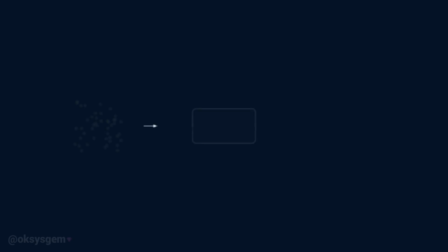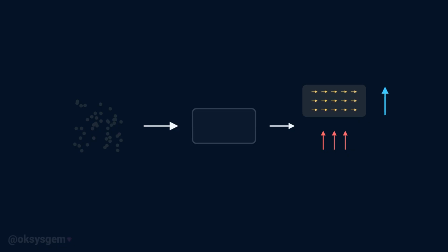Unlike a solid piece of metallic iron, ferrite is a ceramic. The ingredients can be processed into a powder, shaped, and heated until the particles bond together into a rigid magnetic material. During manufacturing, magnetic fields can help orient the microscopic structure so that the finished magnet develops a preferred magnetic direction. Ferrite magnets are not particularly powerful compared with the strongest permanent magnets available today. Their advantage is everything else.